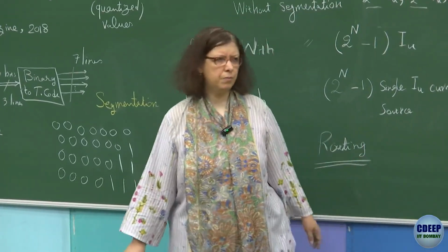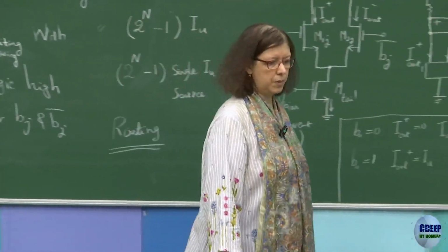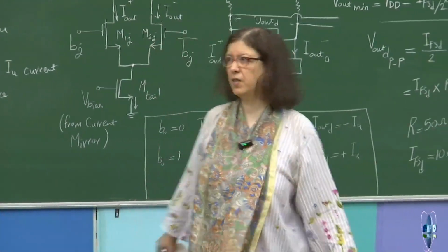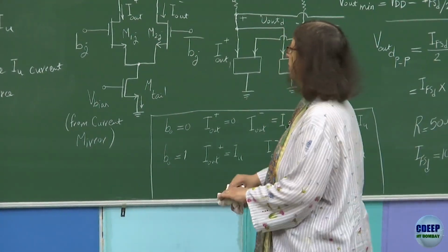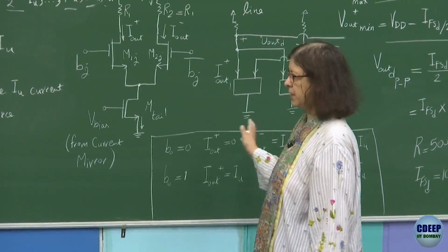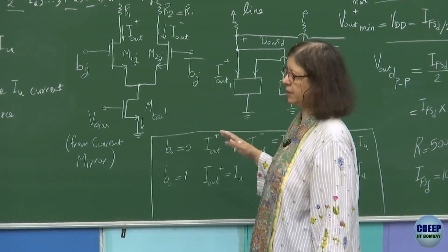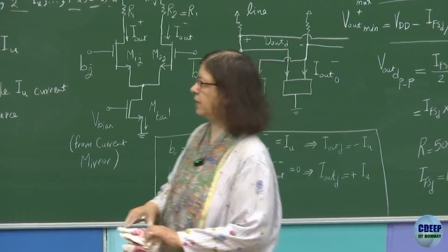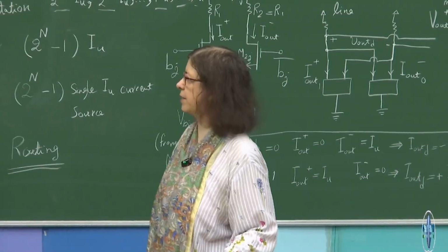The resistor is more often given to us because it's a system level decision; we don't have much freedom to choose R. And VDD also is given. So we will keep the design for later, but now we can look at the mismatch and process variations.